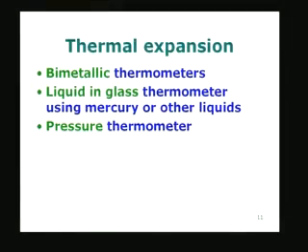It can also be used in many applications. It can be a thermal switch. When it bends, it will make or break a contact, and therefore, it can be used as an electrical switch also. That means that at a preset temperature, it will open the switch, and yet again when it cools back, it will remake the contact, and so on and so forth.